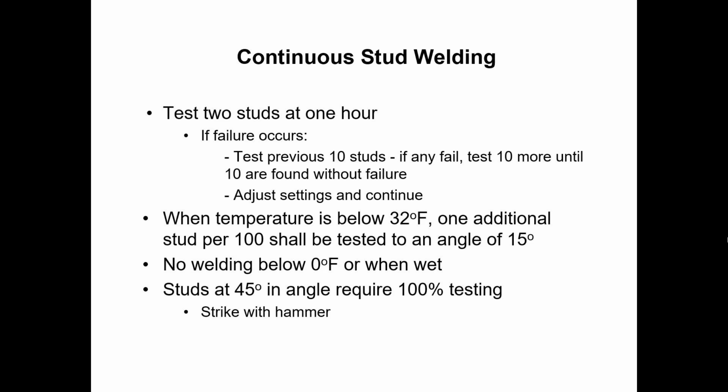And the point of that is just to make double sure that we're not getting any embrittlement of the materials because of the temperature. Similar to welding rebar, no welding below zero or when you're in wet conditions, if it's raining or something.